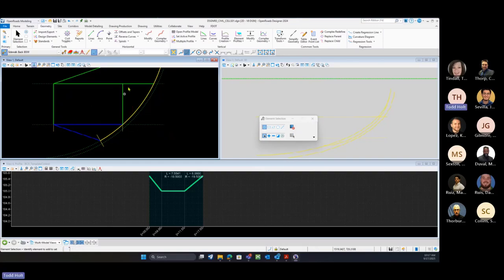Since that's always going to stay there based off of this lower point, the curve point that we have here, I just did a line between points and snap to our front sidewalk. And then I always want to keep it perpendicular off of my sidewalk back. So I switch those two snaps. And then from here, I can build in my ramp off of that one. I'll set that to 2 feet.